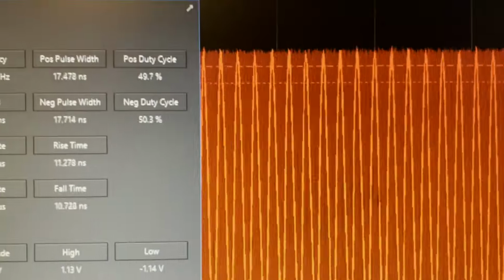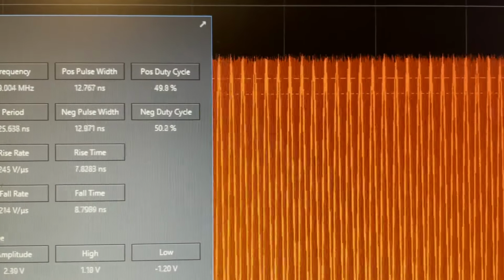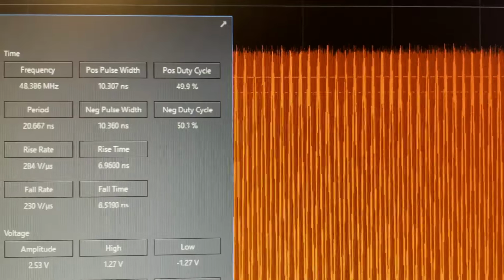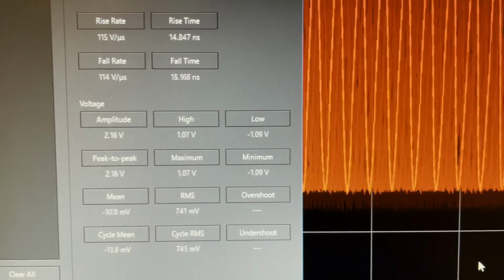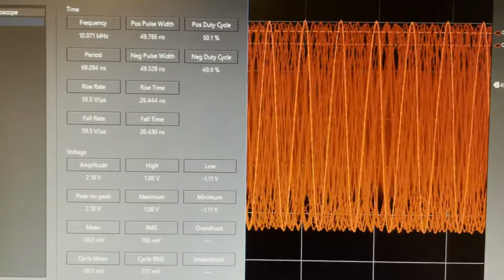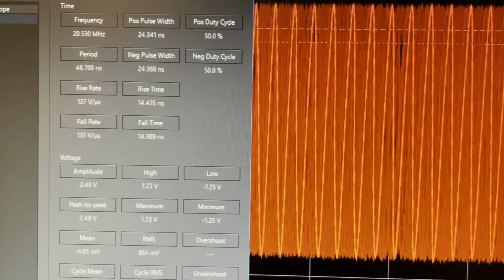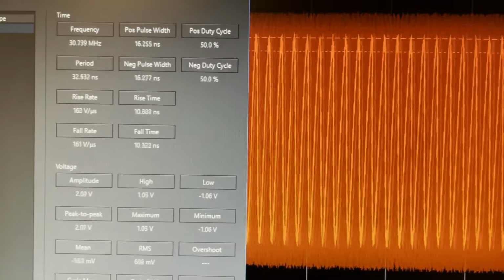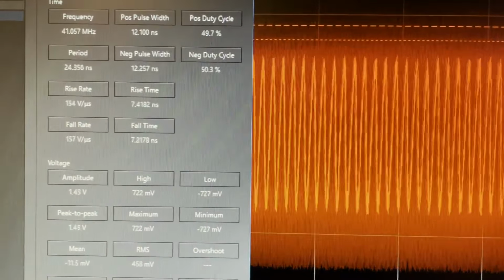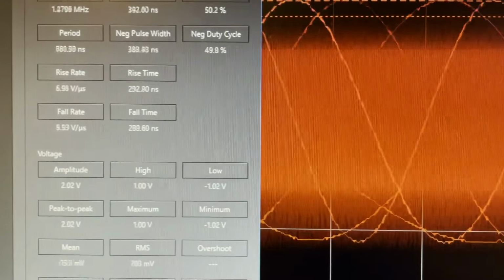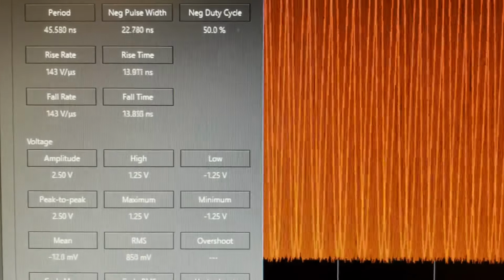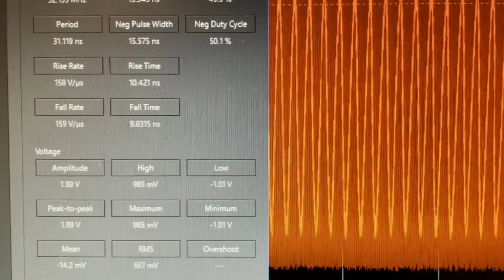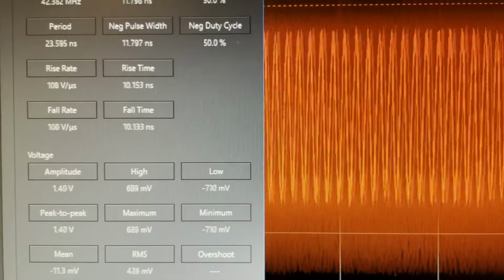Let's watch that top there. See what it does. Really didn't drop that much. That's interesting. Now let's look at that peak to peak. Actually, you can just see it. Look how that peak to peak is dropping. You can see that in the peak to peak numbers. We started out over 2 volts, actually more like 2.5 volts. And it drops